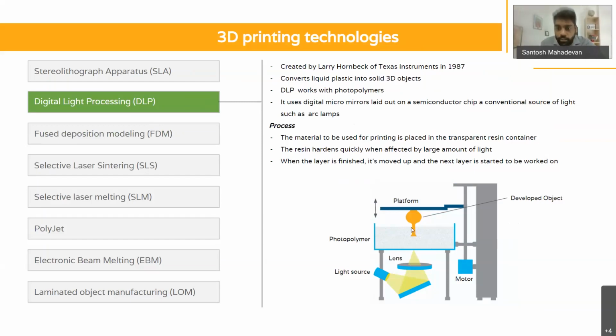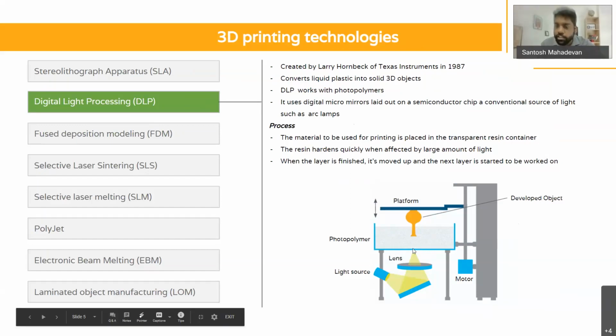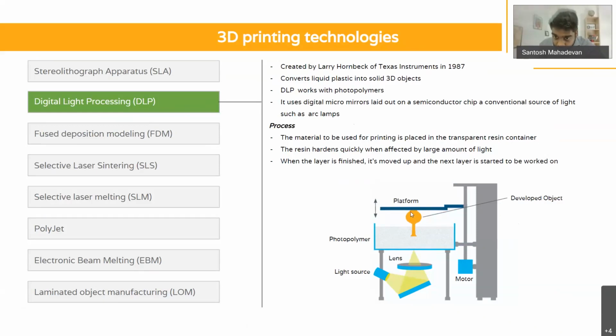Once the first layer is formed as a result of the DLP projecting that cross section, the platform moves the height of one layer, and then it projects the cross section of the next layer. If you were to guess how this vase was formed, this circle with this diameter was first projected, then the platform goes up, and then this circle is projected, and then this circle.